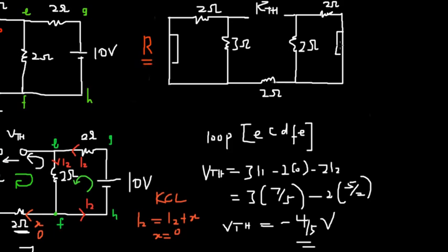Okay, so now from here we know that this 2 ohm and this 2 ohm are in parallel. Because when you traverse through them, in case you've not watched our first video on resistors in series and parallel, you can skim through that video and then come back to this. When you traverse through both 2 ohm resistors, we could notice that there is no other element.